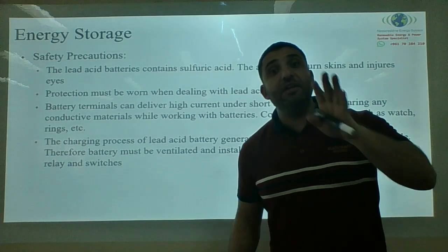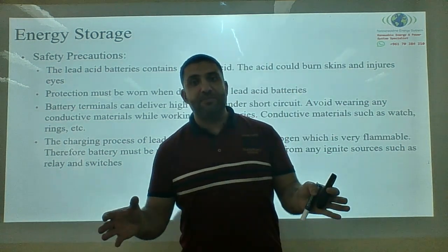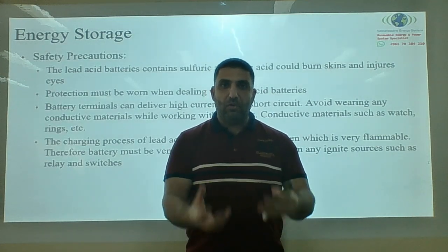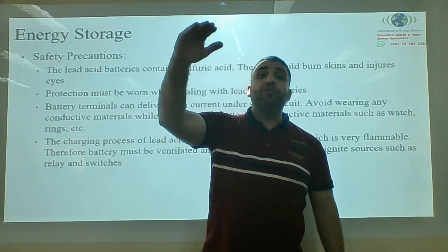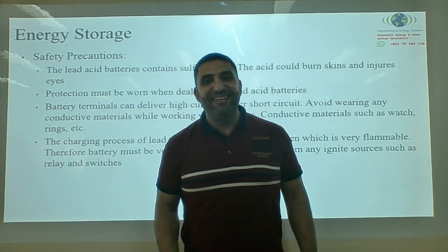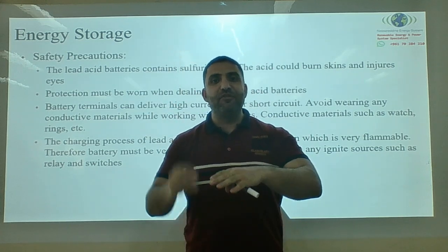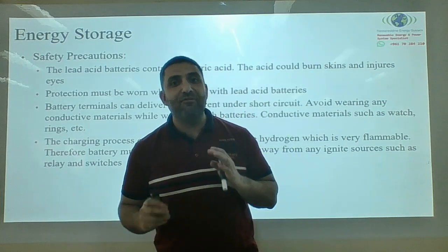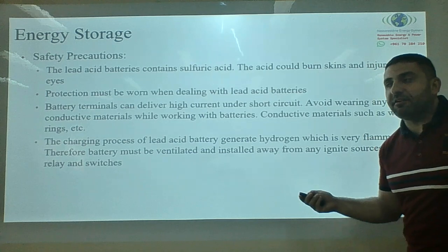Now, it's very important. Sometimes I go do an inspection and I see a lead acid, the old type. They have the water, all the gases go up. On top of it, they have a relay. Guys, the relay, when it switches on and off, it sparks. Switches that spark, avoid this. Avoid it. Guys, this could cause a major fire without you noticing.